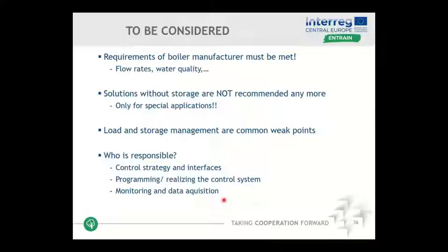I mentioned that we do not recommend systems without storages for obvious reasons. There are special applications, one or another I will show later on, where we can do that, but not for a standard system setup. Load and storage management are common weak points, closely related to who is responsible for defining a control strategy, who is responsible for programming, realizing it, who is responsible for checking it afterwards in the monitoring, who is responsible for the data acquisition so that we are even able to do monitoring and check what our plant is doing. These are very important points. You should define that in the very beginning.